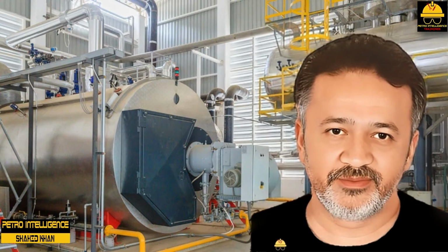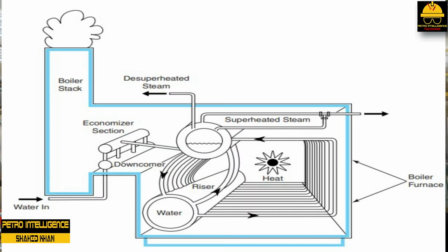Economizer section. The economizer section shown in the picture is used to increase boiler efficiency by preheating the water as it enters the system. This section is a series of headers and tubes located between the firebox and the stack. Temperatures are typically lower in the economizer section than in the rest of the system, but the hot flue gases moving out of the firebox and into the stack still have enough heat to offset energy costs.